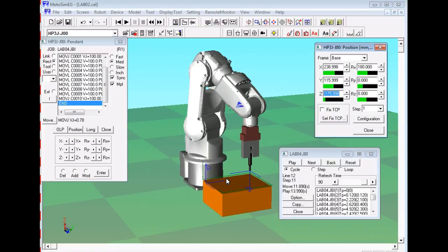It's an animated model. So when you build a work cell, you say add a robot, and then it brings up the list of robots that MotoMan makes. Then you choose that robot, and it pops that robot into your work cell. And then you've got a teach pendant that you do what? You jog it, you teach points, you do everything else exactly the same. Creating a program is a little different, but almost the same. And then you teach your program around that model.